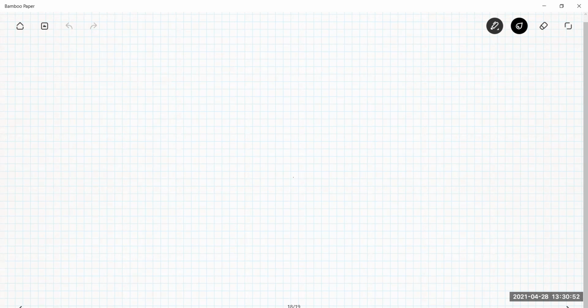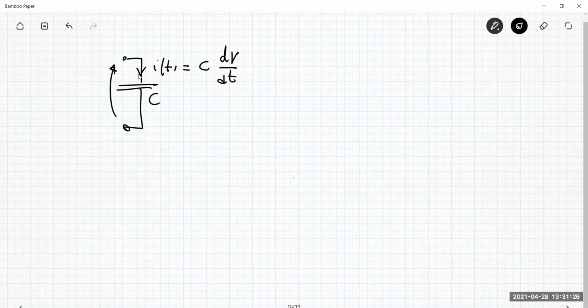So I introduced this behavior of the piezo actuator for this kind of very precise and fast movement. They act as a single capacitance if we look at them for frequencies under the first resonance. So what does it mean? That I have a single capacitance. This is the model for my piezo actuators. It means that the current flowing through it is a function of the time derivative of the voltage across it.